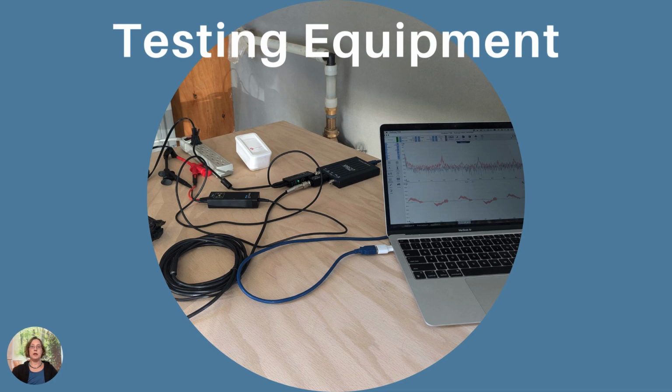The testing equipment I use is a Picoscope 2204A oscilloscope, a Stetzer ubiquitous filter that removes the 60 Hz signal, a Mixig DP1007 high voltage differential probe, a Hantek HT201 20:1 attenuator, a Hantek HT-30A BNC to banana adapter cable, and a Stetzer capacitive filter.